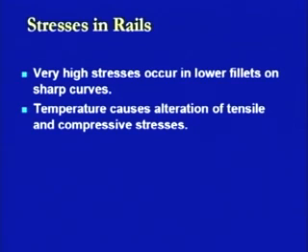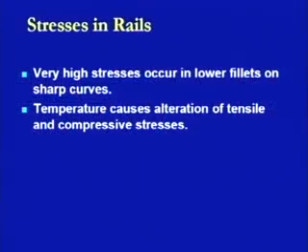Then the another thing which has already been discussed is the temperature variations. Now, as I told you, any track which is placed, is placed at a certain temperature. Now, if the temperature goes below or above this temperature, it is going to create an effect in terms of either contractions or expansions, depending on the variation of the temperature. As soon as this type of variation is there, it is going to create tensile stresses or compressive stresses in the system.